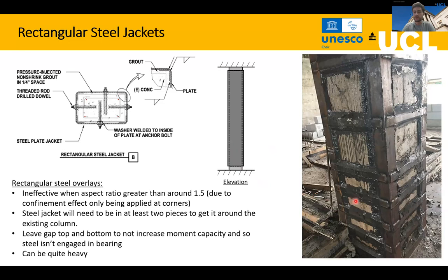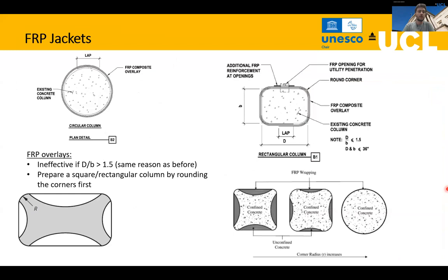Also, you will need some specific capacities to weld this type of plates and to ensure that they will work as a confined element. Another possibility is to include these FRP bands. In this case, this type of bands works very well in circular columns because you will have the confinement of all the area of the column or element that you are analyzing.